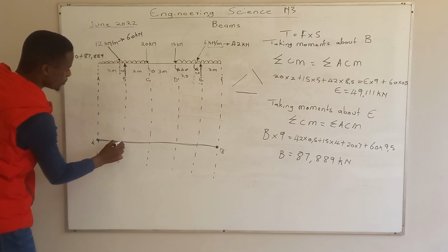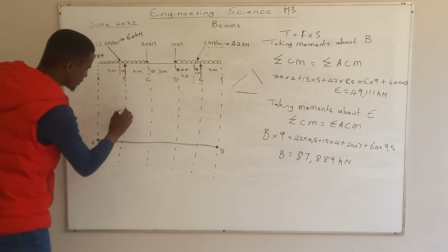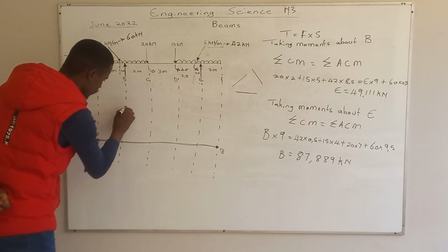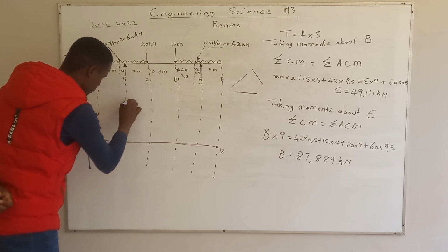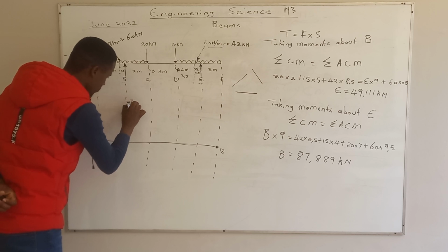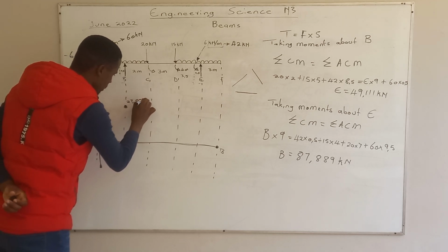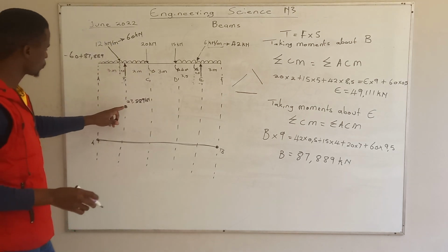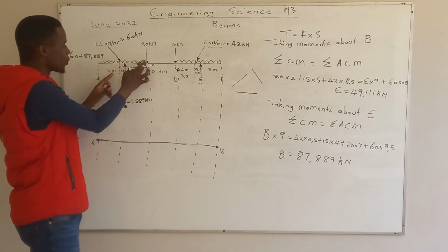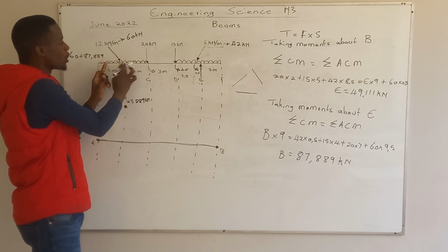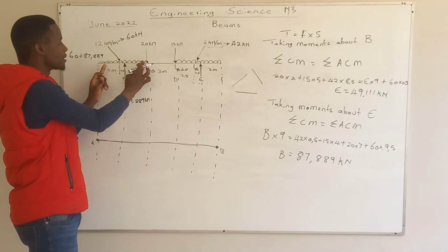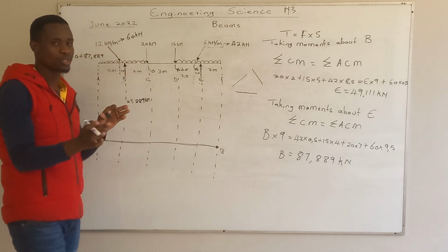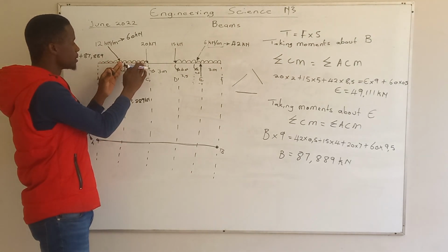You're going to measure from here up until where it says 27.889. For me, I'll just see if it's here. 27.889 kilonewtons. Then from this one, already we used the UDL because it's this side. So you're no longer going to be using the UDL for this distance, but you're going to be showing it. Don't use the UDL when you're calculating this one.